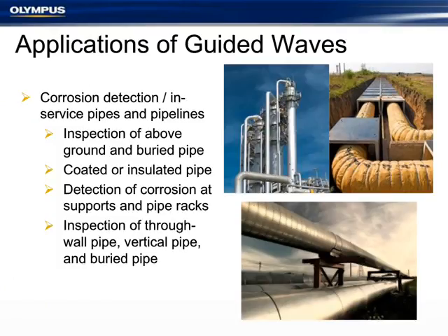If we only have a certain area, we can actually look at buried pipe from a single location and not have to completely unbury the pipe to get a general inspection. If it has some coating or insulated pipe, we're actually able to leave that on, where with traditional ultrasonics we would have to remove that completely. We only might have to remove it depending on where the collar needs to be placed.